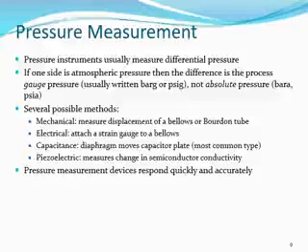The second type is electrical. There is an electrical device to measure the pressure by measuring the resistance. The pressure is transmitted into an electrical signal, and according to this signal there is an electrical gauge showing the pressure. And the third type is capacitance. The diaphragm moves, and on the capacitor plate it generates a signal to indicate how much the pressure is.